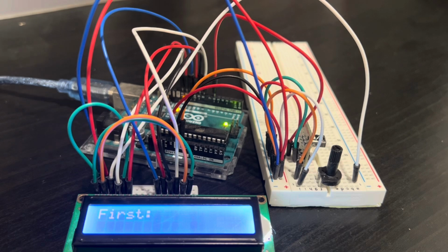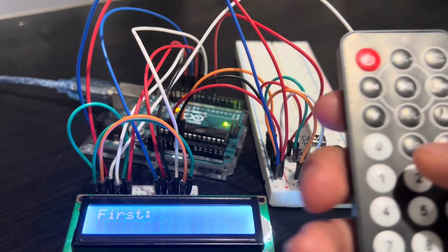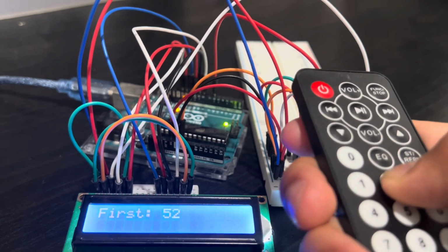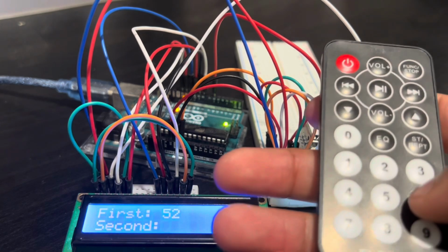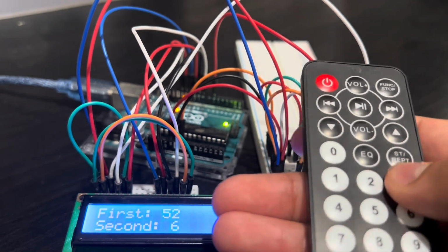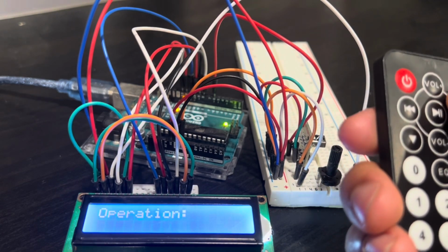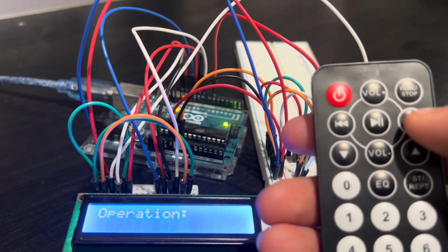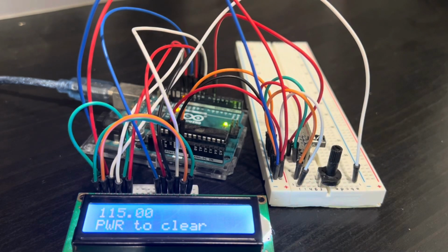So here's a small demonstration of how exactly this works, right? So here I'll put the Arduino remote on the side. So it's prompting me for my first number, right? So let's put in 52, and then we press the stop button to transition to the next state, which is the second number. Let's put in 63. All right, and we press the stop button again, and this transitions to the third state, which is operation. Then we put in add, subtract, divide, or multiply. Right, let's add the two together, and that yields 115, which is the correct answer, by the way.